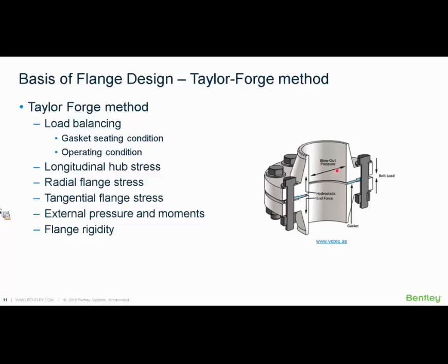And once you are in operation, there would be an additional hydrostatic force as well, which would try to pull apart the flange, and then you need to have enough bolt load on the bolts so that your gasket remains in its position and keeps on sealing the flange joint.